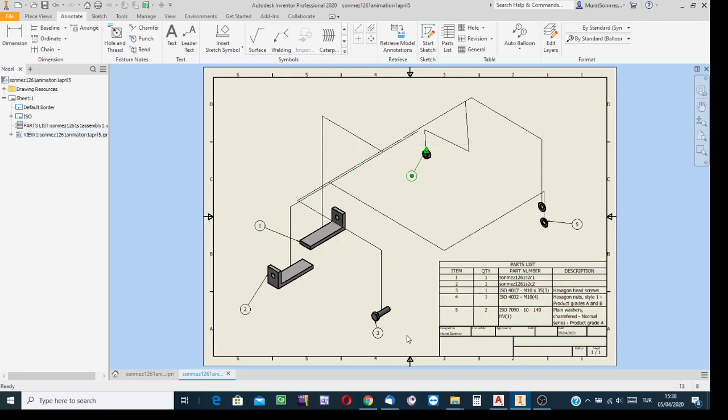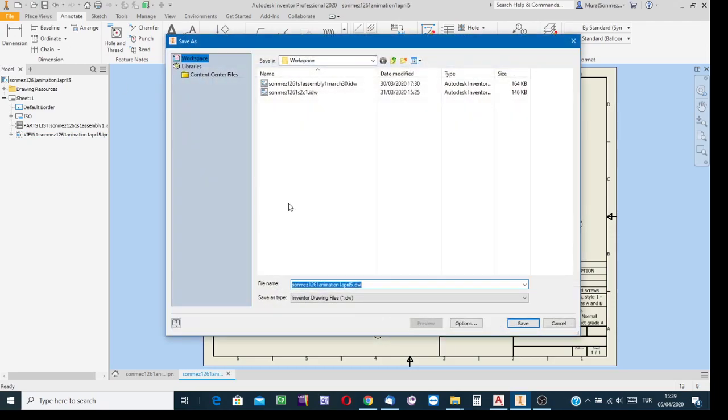In the previous video record, I talked sufficiently about how an assembly drawing is created, how the balloons can be shown, and how the parts list is edited. Here, this is just to say that it is possible to create such an exploded diagram, and on the exploded diagram you can show the balloons and even add the parts list. Okay, save this file.